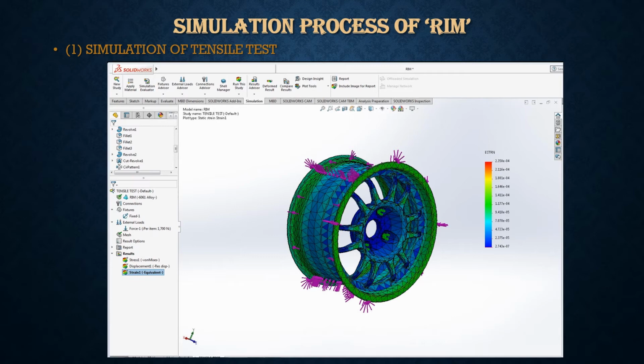The material that I use for this rim is alloy 6061, and go to the fixture where fixed geometry to select the fixed point, and then external load force, select force, insert the value of force that I use, which is 1700 Newton, and then go to create mesh, run the study, and the simulation will show strain, displacement, and stress. And the final one is generate report that I will give at the end of this slide.